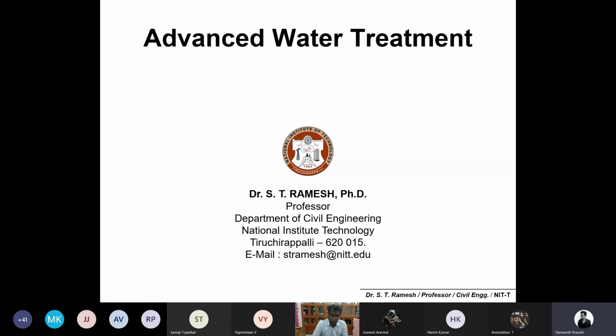If you want to remove salt, you may use reverse osmosis and other dialysis technologies. If you want to remove pathogens, you use some sort of advanced treatment technologies for complete destruction of pathogens. If you want to remove nitrate, you may have a special technology. If you want to remove odor, you have a special technology. If you want to remove color, you have special treatment methods. So materials that cannot be removed in traditional water treatment systems, you can plan for in advanced treatment systems or advanced treatment technologies.